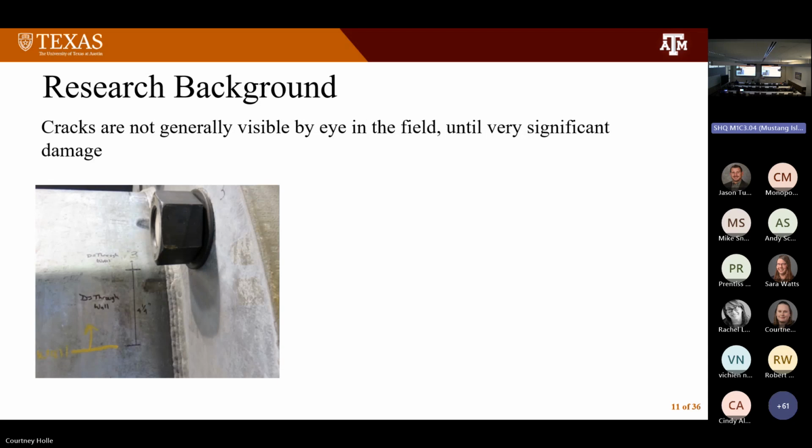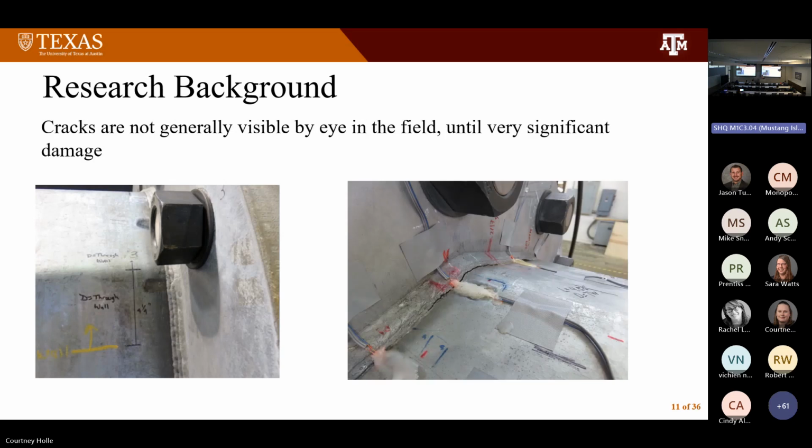So historically, what we used a lot of times were conventional ultrasonic inspection techniques, where you could find some of the cracks in the poles, but it was hard to locate some of those. By the time you can see it, like we see in this slide, where you can see some of the cracking over here, usually the fatigue life is greatly diminished to the point where, if you can see it, you have a major problem, you need to move quickly, okay?